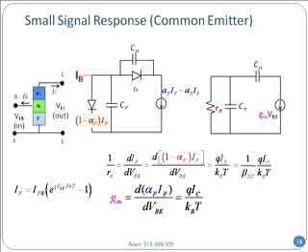So therefore, in the transconductance, I'm just taking that with respect to VBE. Again, you take the derivative. If you take a derivative, you pick up a 1 over kT, q over kT, and that's your final expression. And so, if you wanted to know how the current source changes when you change your base signal a little bit, then you will just cross multiply and write it as gm multiplied by VBE. And that's what is done in the small signal equivalent circuit on the top, this magenta on the top.